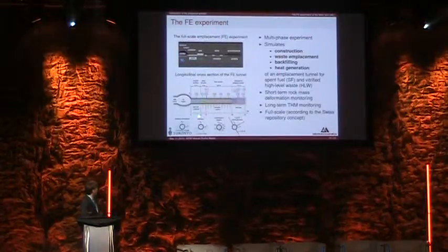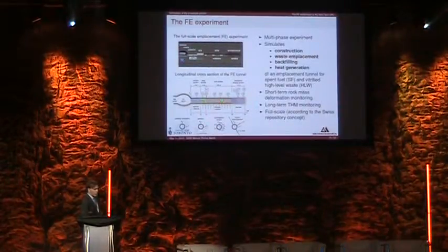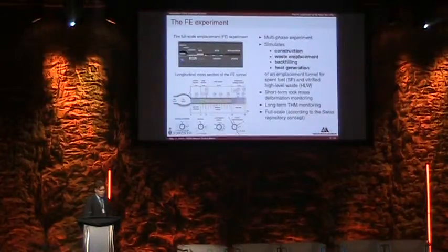It's essentially a 50-meter long tunnel, 3 meters in diameter, with different support measures. In the central section, which is the one we model, we have shotcrete and some anchors, and some steel sets at the end, here close to the starting niche. This tunnel was excavated parallel to the bedding plane strike, which is the case that we were interested in.